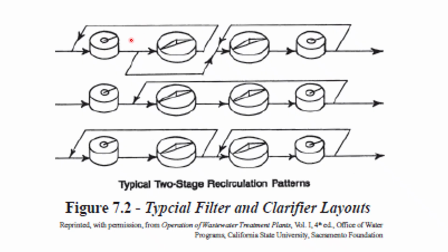We're reducing the suspended sediment load with this recirculation loop, and we're making our organic removal more efficient with the second circulating loop. In this case, we're probably satisfied with the suspended solids removal with the primary clarifier, but what we're doing here is we're focusing on that dissolved organic load. So we're trying to get as much out of that with this scheme as possible.